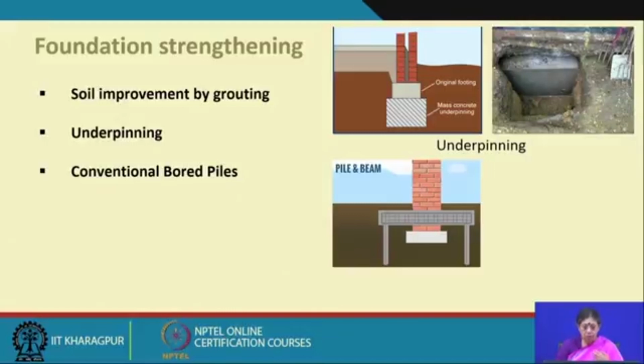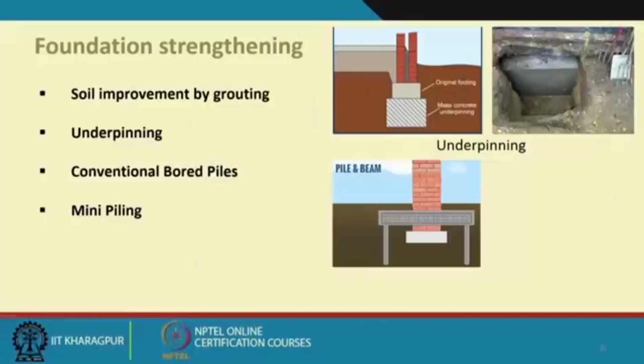And there is also the question of mini piles. Mini piling is when the piling is done through the foundation, cross piling and other. So, boring the holes and then putting concrete into them with the proper reinforcement, so that they can take the load. If you remember the various options which came for the Leaning Tower of Pisa, there were many such suggestions which were given for that.